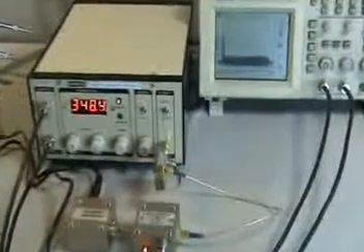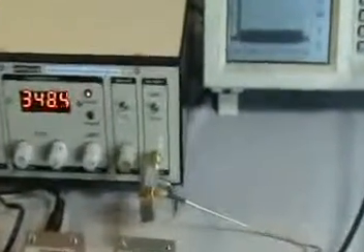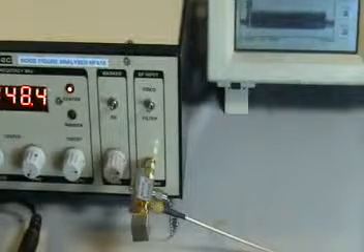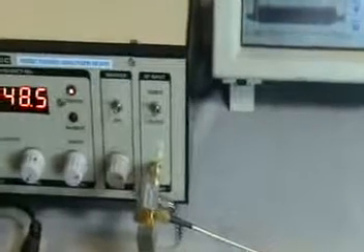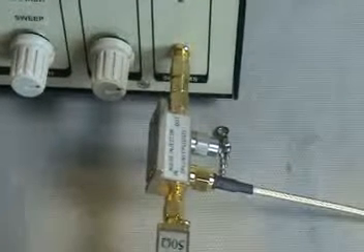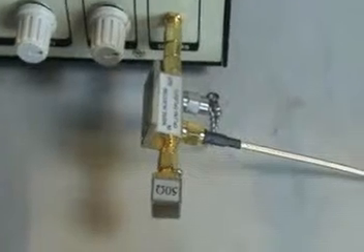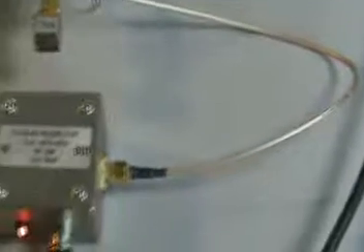That shows that this particular termination has a very high return loss, and we must strive to build all our systems with impedance as close to 50 ohms as is physically possible, in order to keep the noise figure of our system under check.